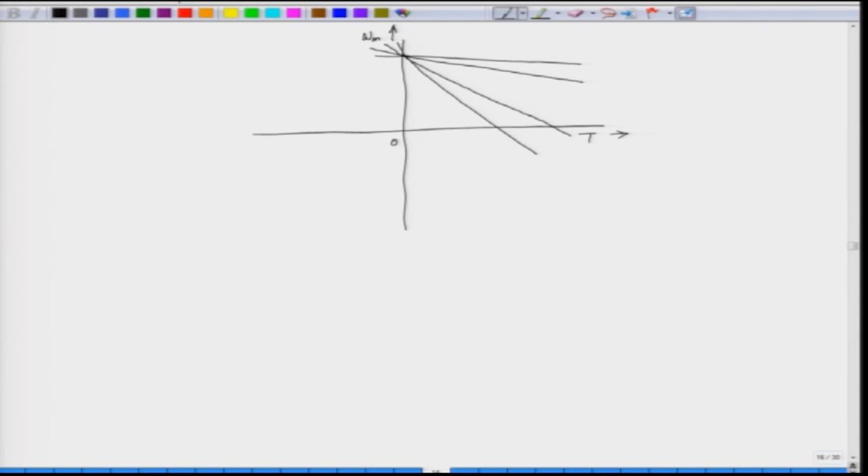Similarly, if we go for reverse motoring, we have the profile like this, and if we further increase the resistance, it changes like this. So this is, let us say, the no load speed in the forward direction omega m naught, and we have the no load speed in the reverse direction minus omega m naught.